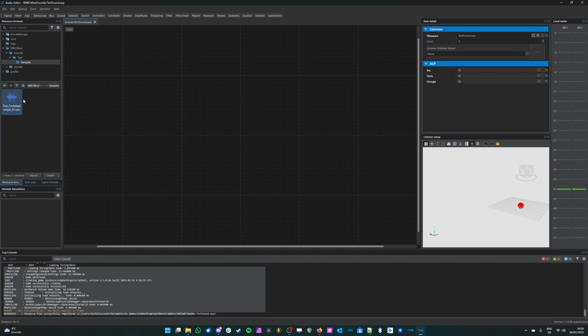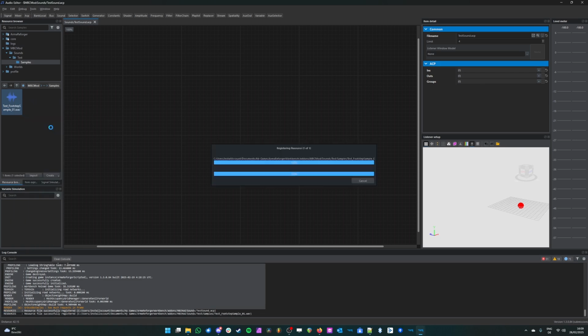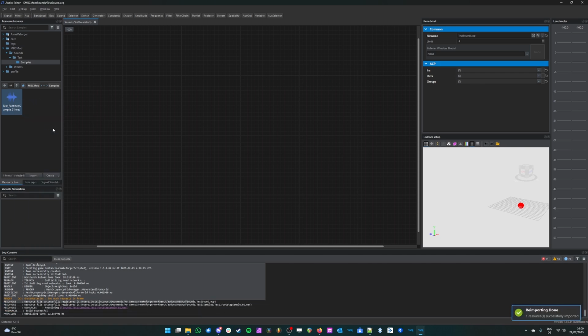It works, right? Wrong. Just like pretty much any other file in the Enfusion environment, files need to be registered. And we do this by just right-clicking it and then going on register and import. And this is very important because if we don't do that, the file will not be able to be referenced in, well, other places within Enfusion. And this can lead to some nasty errors. And it's been an issue that I've seen quite a few times, so keep an eye out for that.